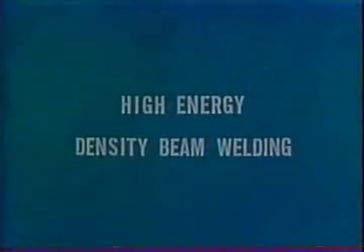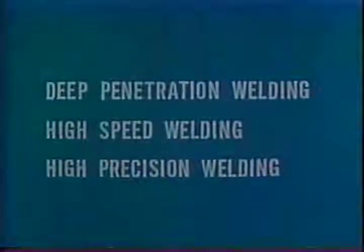Due to the so far mentioned features, the welding by a high energy density beam is superior in areas such as deep penetration welding, high-speed welding, and high-precision welding. However, a defect called spiking, inherent to deep penetration welding, is likely to occur.